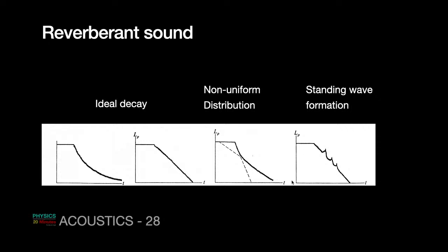Somebody has done a project calculation of the standing wave formation in a bathroom. Every room supports some standing waves, and those are the resonant formations at which the sound intensity increases. So at those frequencies you will get higher intensities, otherwise it is dropping. So reverberant sound decays in different ways in different rooms.